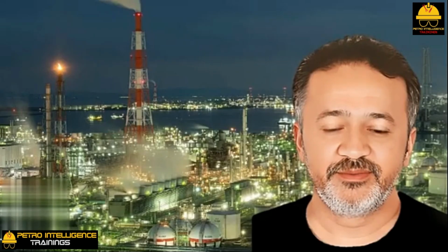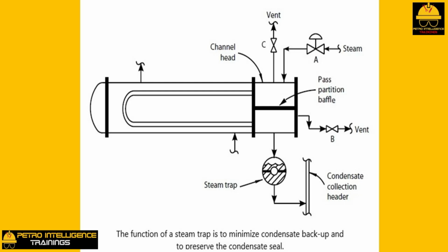Corrosive steam. If CO2 is not vented off from valve B, then it will begin to dissolve in the condensate to form H2CO3, carbonic acid. This acid causes tube failures due to acidic corrosion. Venting gas below the pass partition baffle will stop this corrosion.